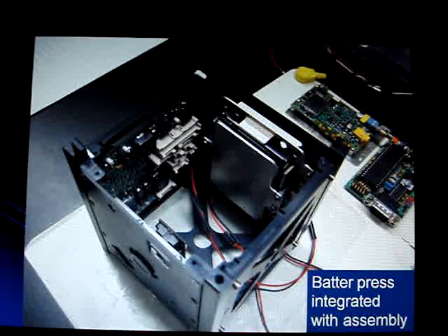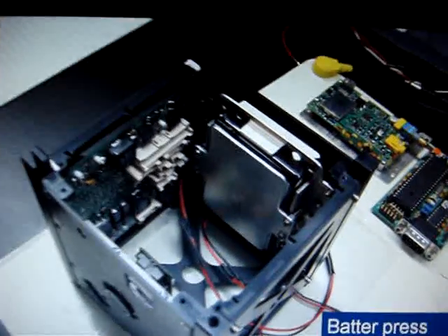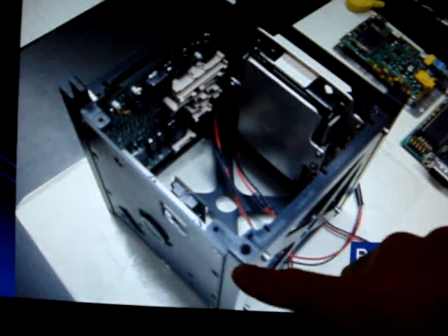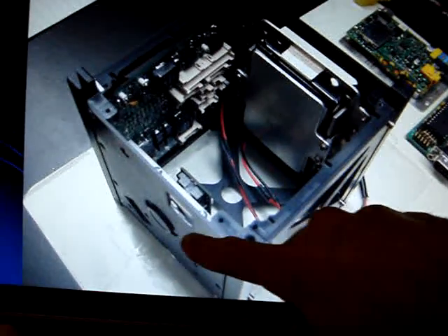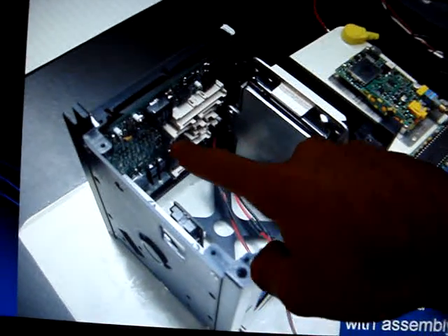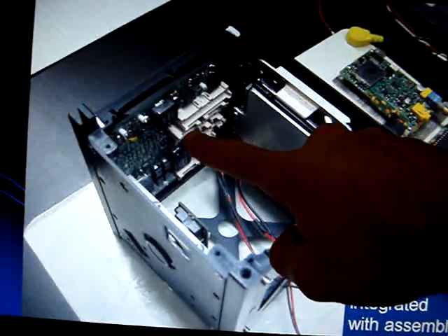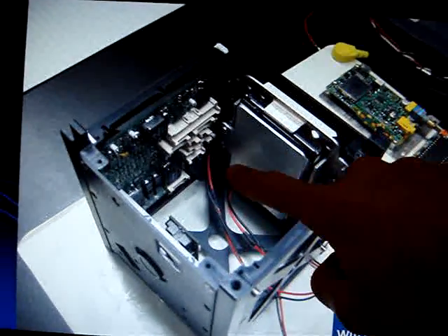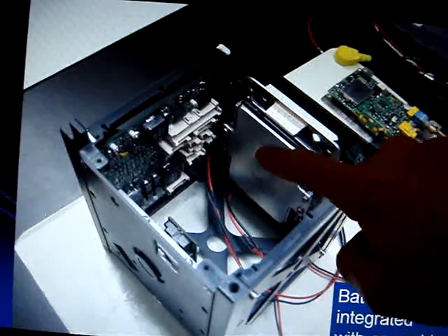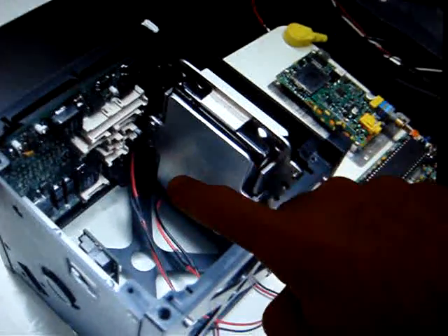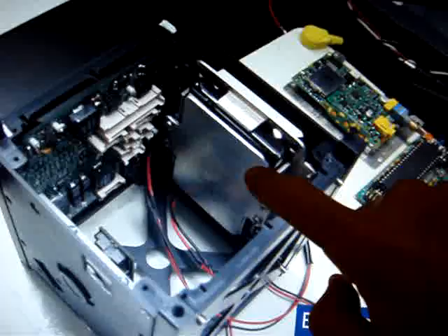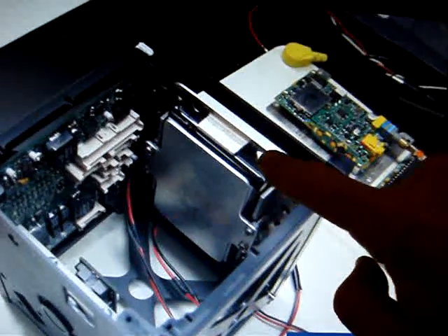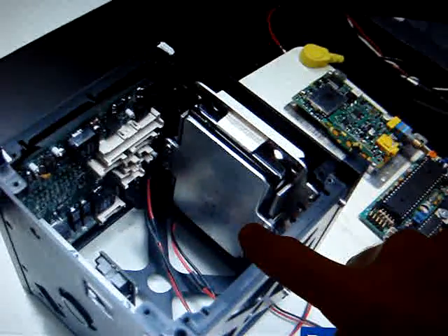Here's another assembly view. Now the satellite is sitting upright, and you can see the front axis panel, the imager, the EPS, electrical power system PCB. An example of a secondary structure right here, this is the battery press, this metallic plate with screws at the end, and it's basically responsible for holding down the batteries to this larger plate that's attached to the structure.